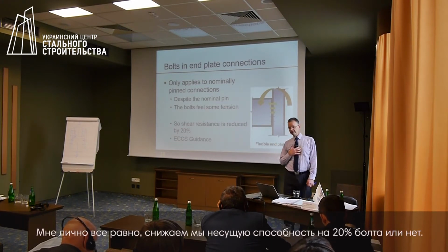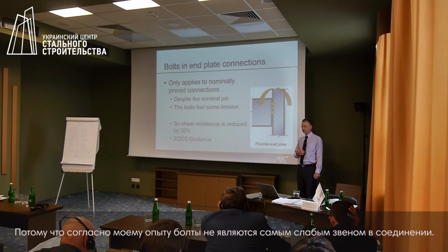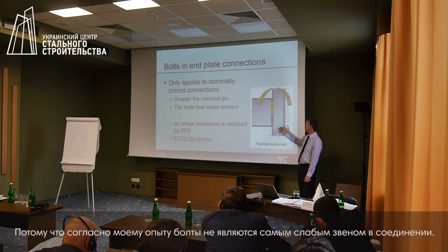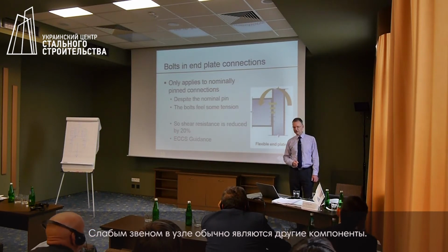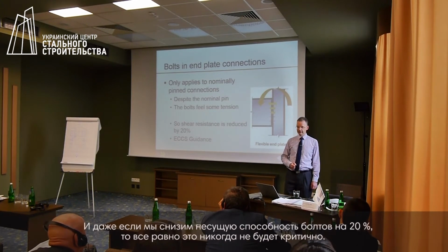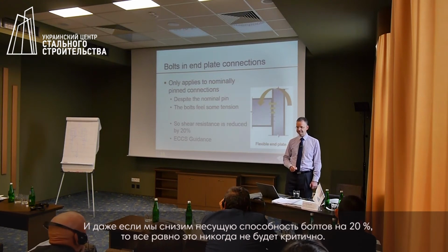I personally do not care that we have reduced the resistance of the bolts by 20%, because in my experience, the bolts are not the weak link. Other components within the connection will be the weak link, and even if I have reduced the resistance of the bolts by 20%, that never becomes critical.